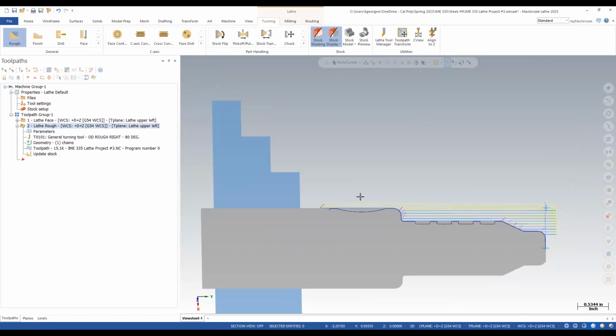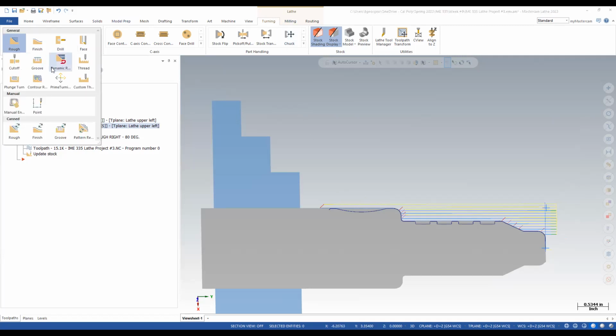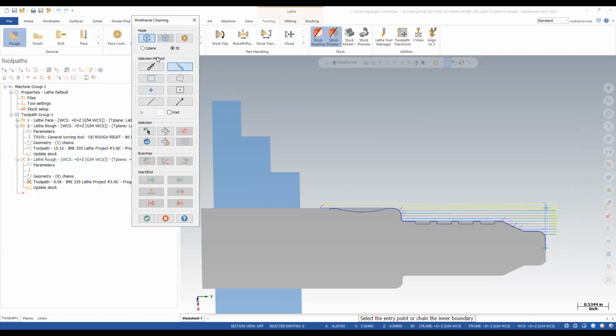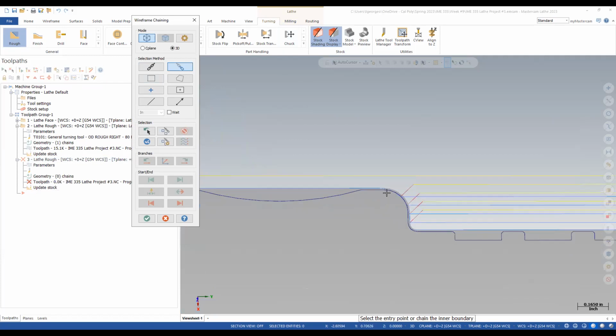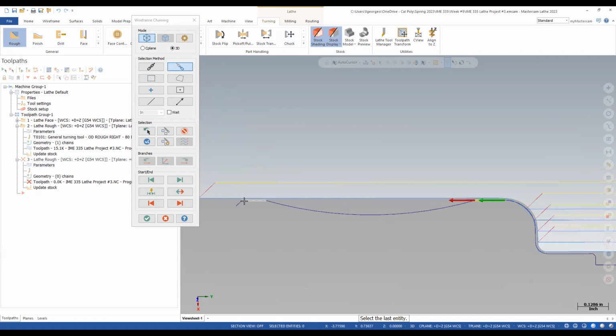We can't plunge with the CNMG, so we're going to switch tools, and we're going to go ahead and rough turn right over here, rough. So when I rough, I want you to rough from here to here. I don't want you just to rough the radius. Why do you think that is? It's smoother to go ahead and just come in from the outside and plunge down than just doing the radius. You never want to do just the theoretical exact boundaries. You want a little overlap.